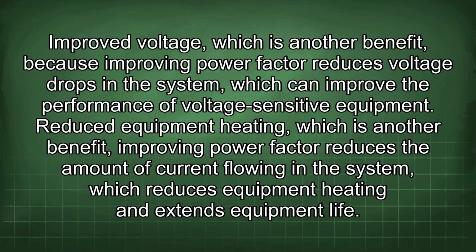Improved voltage is another benefit, because improving power factor reduces voltage drops in the system, which can improve the performance of voltage-sensitive equipment. Reduced equipment heating is another benefit. Improving power factor reduces the amount of current flowing in the system, which reduces equipment heating and extends equipment life.